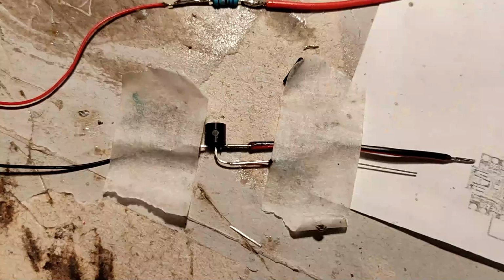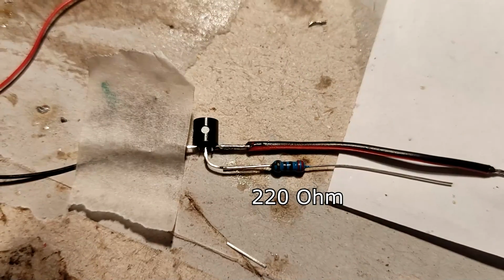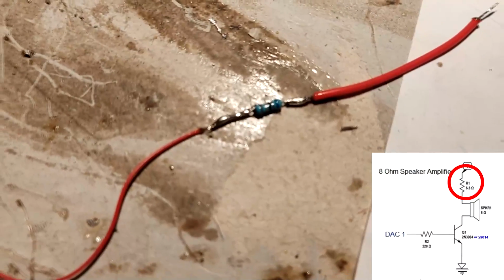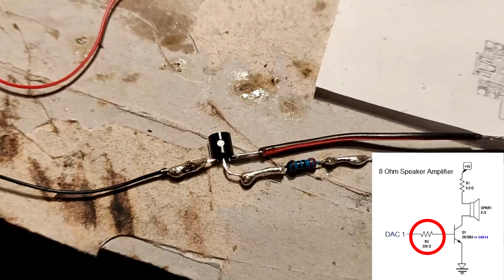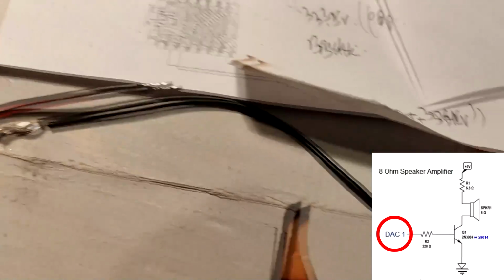Don't forget the sleeve, I have to desolder it. Then I soldered the 220 ohm to the base central pin of this transistor. Here you have the wiring diagram with the 6.8 ohm resistor, the speaker, the transistor, the 220 resistor, the wire to the ground and the wire to the Arduino.